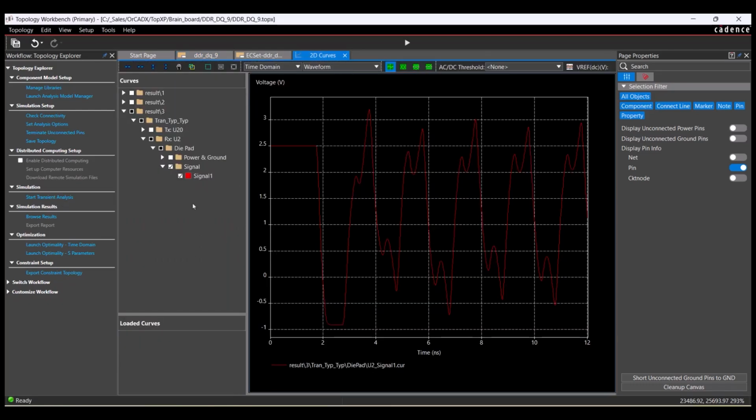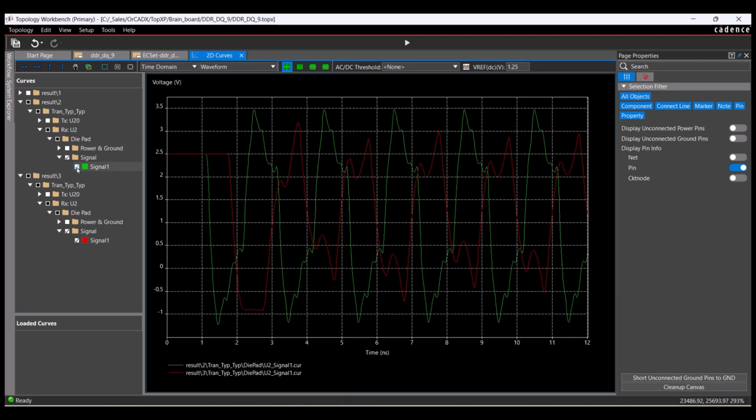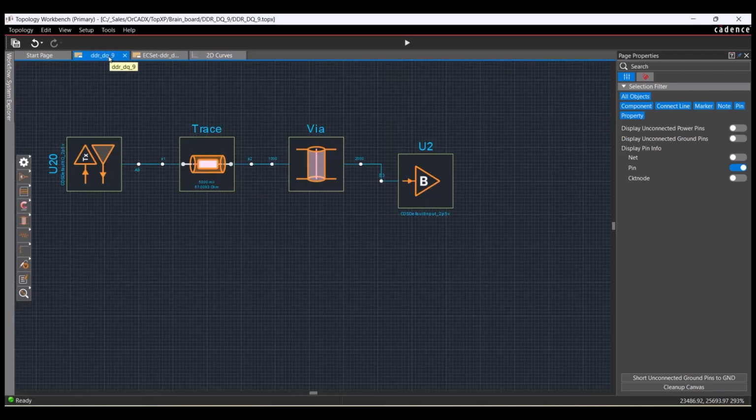Now you have those results available to you to look at, and you can then compare and contrast those results with previous results. So you can overlay multiple simulation results all at the same time. So now you're definitely in a mode where you're experimenting with what that ideal interconnect should be. And again, let me pull this back to the constraints we talked about earlier. Now you're trying to experiment with how many vias can I handle? What's the max propagation delay I can handle?